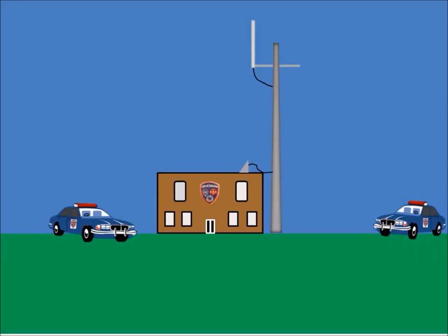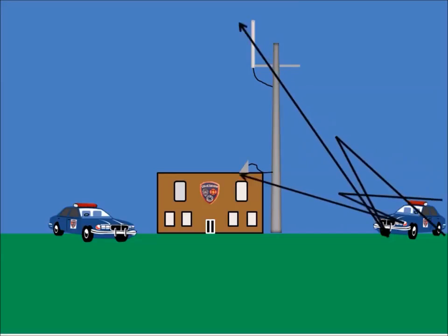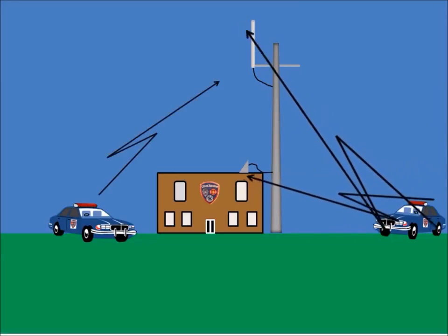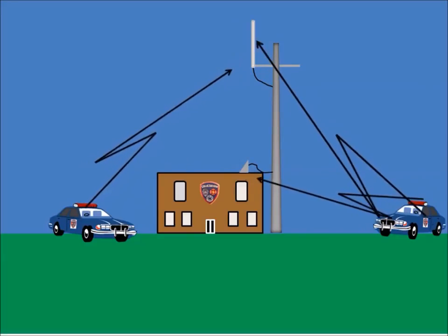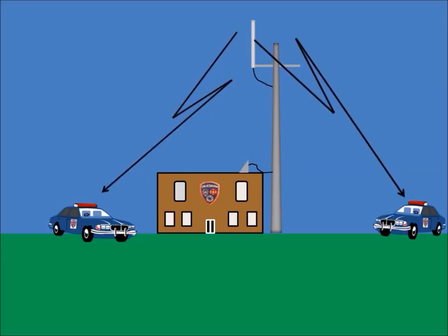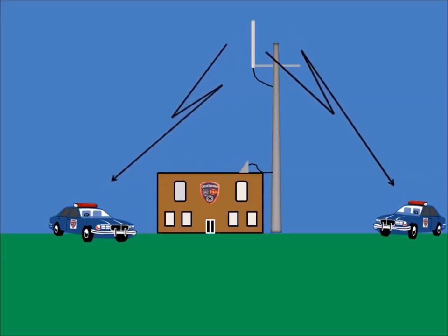If they were to transmit at the same time, this may interfere with each other. This would be heard by the dispatcher because the user signals are competing with each other. Unless one is significantly stronger than the other, neither may be understood. If one subscriber does not hear the other, there may be less situational awareness requiring the dispatcher to repeat the message traffic for the benefit of the other subscribers.